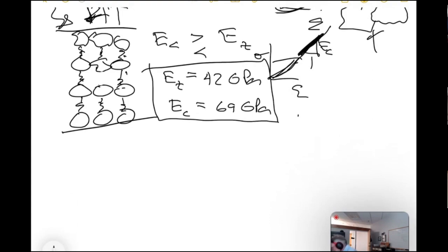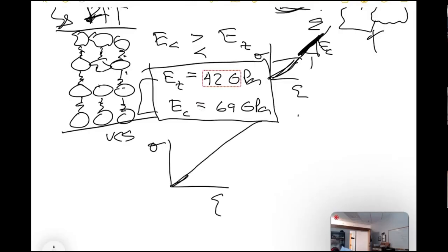And of course, if the granite has been created in such a way that there's almost no initial microcracks, then these things are almost the same. Okay. This is also a thing that is typically never really thought about in rock mechanics. What people typically just do is they do a UCS test, they monitor stress strain, they never even care what's going on here. They just do this and it breaks, and they take the slope and say that's the modulus and they're done.